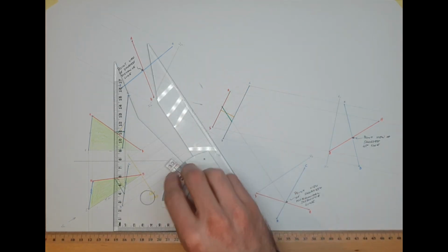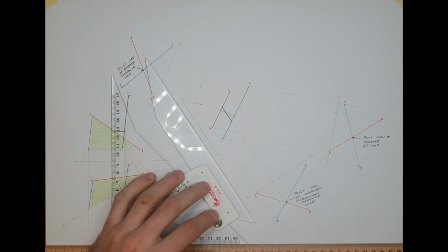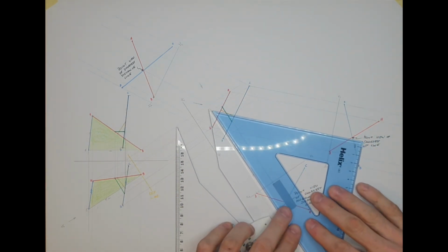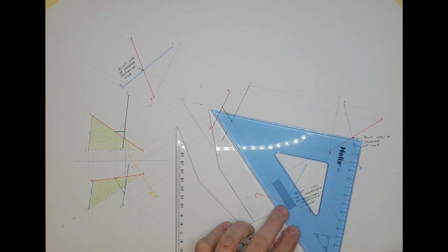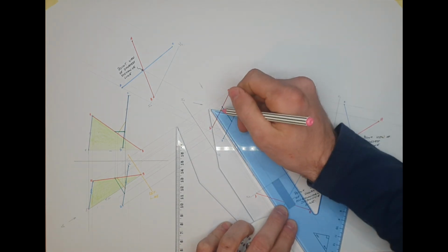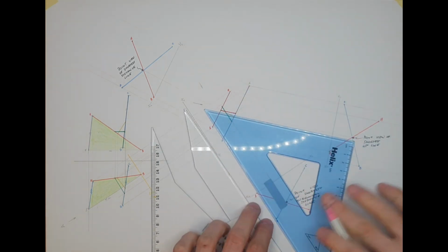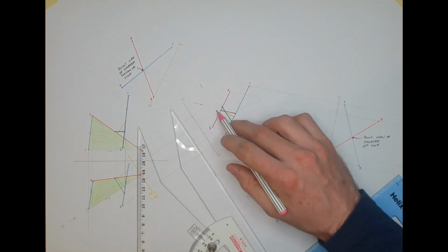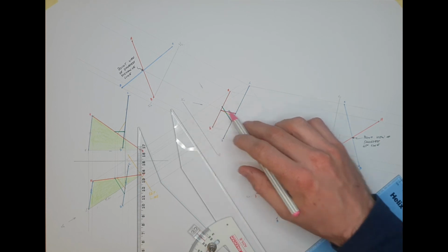I'm going to project the point view based on the angle of my original projection, and I'll project that back up here. And what colour was that? That was a pink line, as I remember there in SolidWorks. So I'll just keep with my colour scheme again. There we go. That is the shortest line that lies at a 45-degree angle to the horizontal plane.